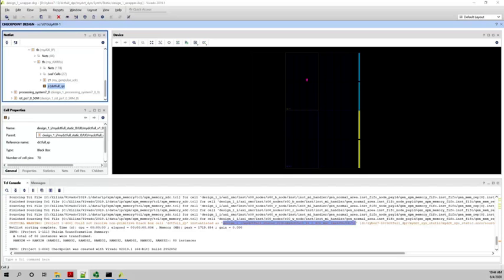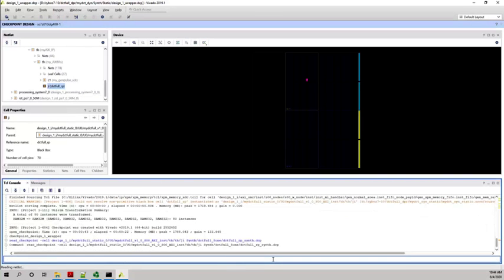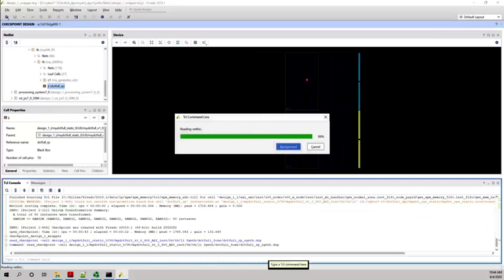You have to load in a particular synthesis file, which is the one we want to use, the one of the DCT 8. Because when we create the reconfiguration partition size, we always have to use the largest one. So we're going to fill it up with that information. Here we go. So now it's going to be filled up in a little while.